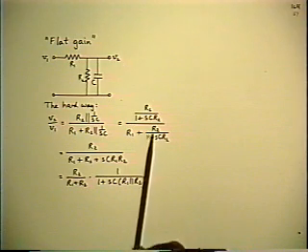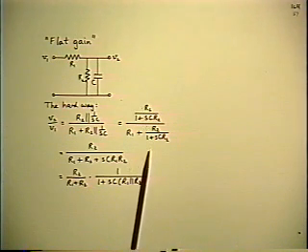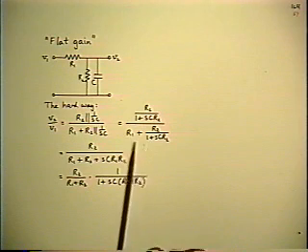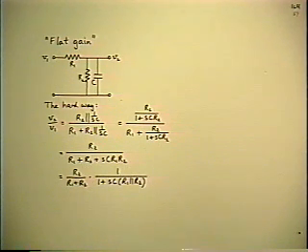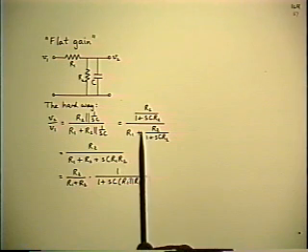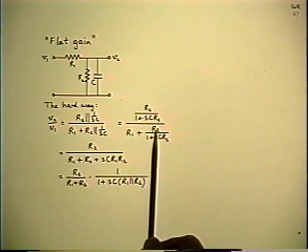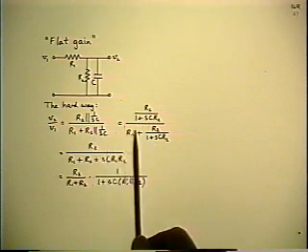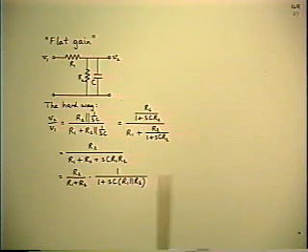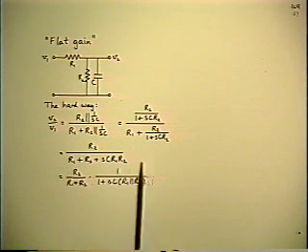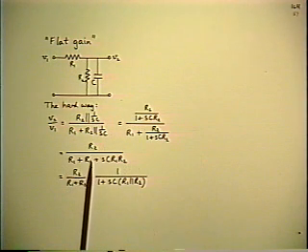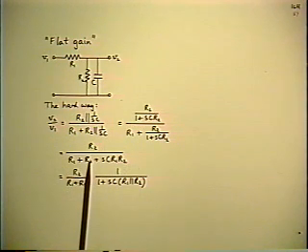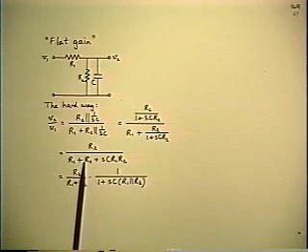The next line of algebra means you get rid of the internal fractions, because the objective is to write the answer as a ratio of polynomials in complex frequency. That is, you want the numerator to be in the form of 1 plus s squared plus s cubed, etc. You want the denominator to be in the same polynomial form. So here's the penultimate line, and one step left is you want to make the leading term 1.